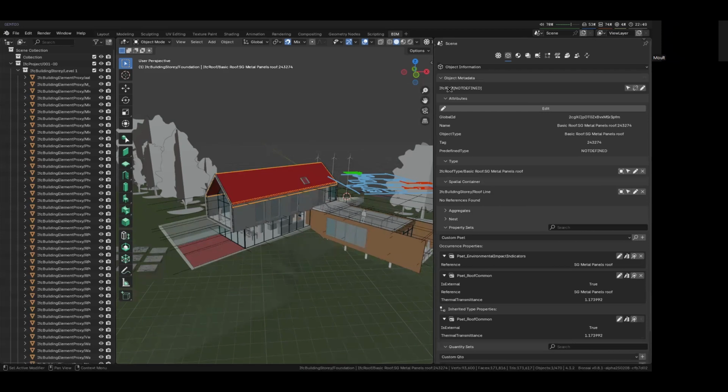And so the first level deep is a roof, and the second level deep, in this case, is not defined. And this is how IFC works, in that only the first level deep is mandatory. The second level deep, you can omit it, or you can choose from some classifications, or you can actually override it with your own custom classification. And that's really quite cool because many other classification systems are locked and set in stone, right? You can't invent your own Uniclass classification code. You have to choose what's given to you. Whereas in IFC, if what's given to you is not appropriate for your project, you can just add a new one.